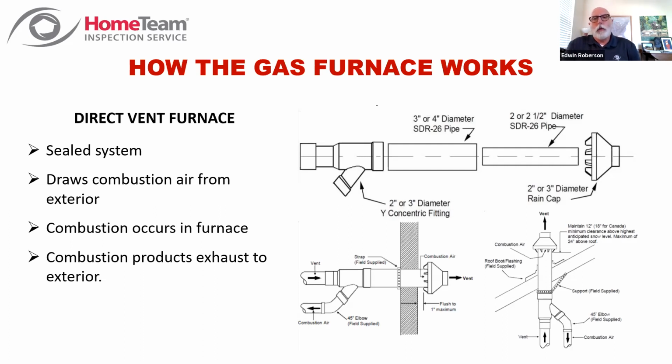So anytime you have an existing home that has a crawl space or an attic with a furnace in it that's drawing air from that space for combustion, and you decide to seal that space, you also have to fix that furnace system so that it can draw air from outside. So that's something to be aware of in renovations.